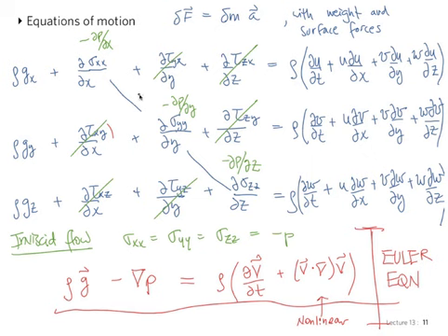And I finished by saying that if you specify these equations for the case of inviscid flow, then all shear stresses are zero. So with the green here, we scratched out all the shear stresses, and the normal stresses would be due to pressure only. And for that case, we wrote the equation in this form, which is the Euler equation.